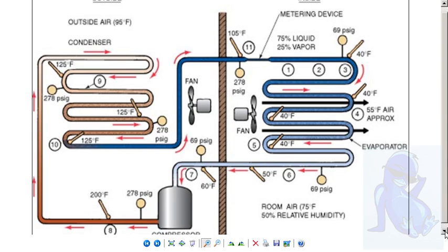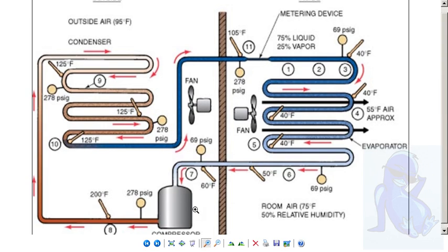You have a compressor. In your outdoor unit, which is called your condensing unit, you have a compressor in there. You also have a coil around it and a fan motor. That is what your outdoor condenser is. The compressor is taking refrigerant gas, it's compressing it, and it discharges it out as a very hot discharge gas, like 200 degrees Fahrenheit.